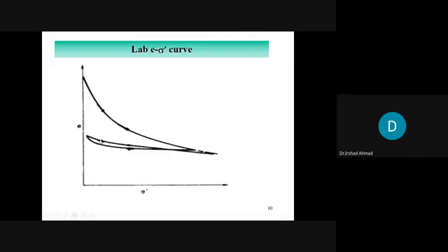And this curve is called recompression curve because you are recompressing the soil specimen, right? You took the specimen to a particular stress level and then you decrease it, and then you are again taking the soil specimen to the same stress level, so you are recompressing the soil specimen. This curve is called recompression curve.